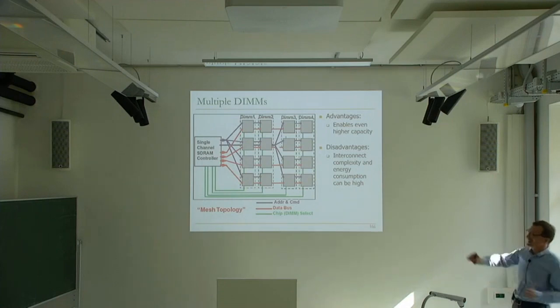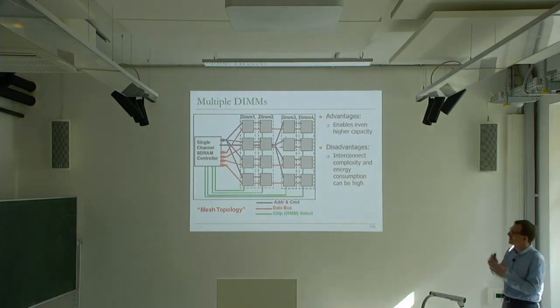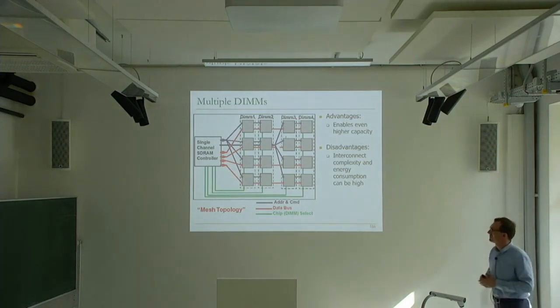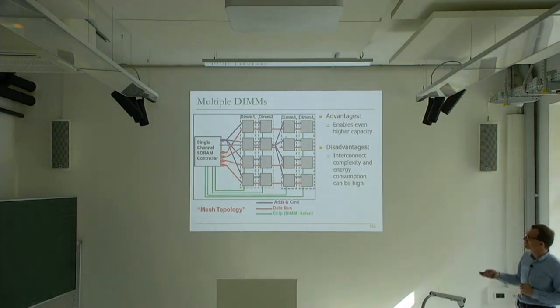This is where 3D stacking can be useful. If you can stack a lot of memory on top of each other, these interconnects become much shorter. Of course, the question is how do you design those interconnects. It's a research problem today, actually. But this is how you get more capacity in a single DRAM chip, with a single DRAM channel. OK. Of course, scalability is limited by this now, your interconnect complexity. That's why interconnects are very important. How do you interconnect them is important.